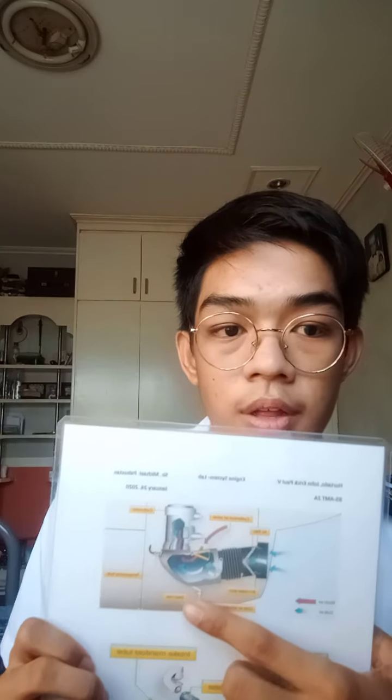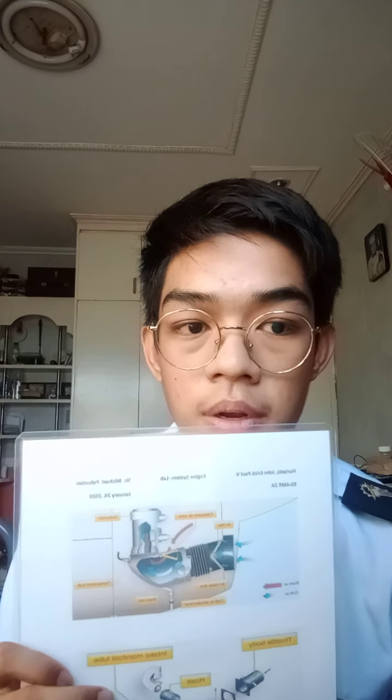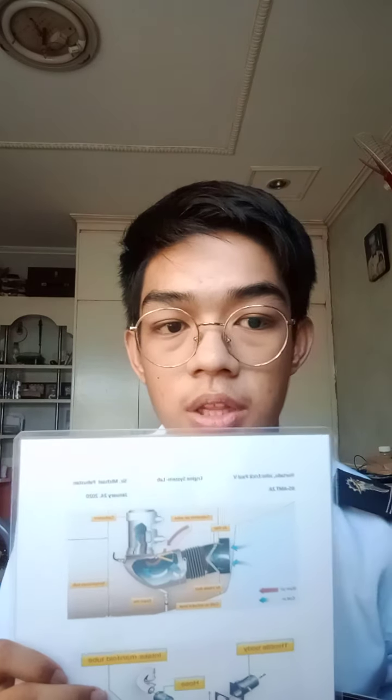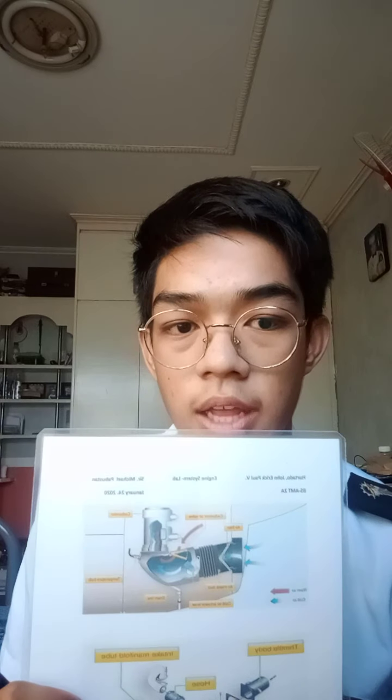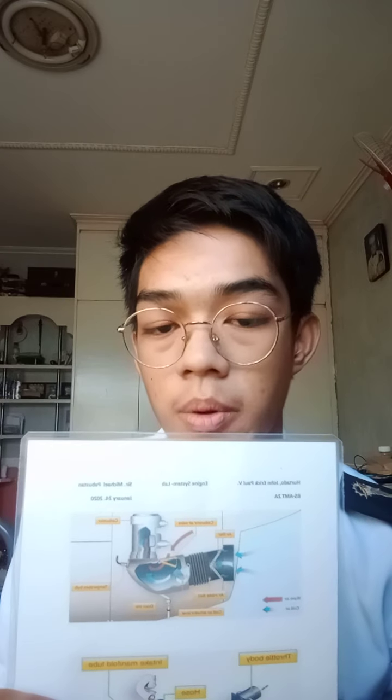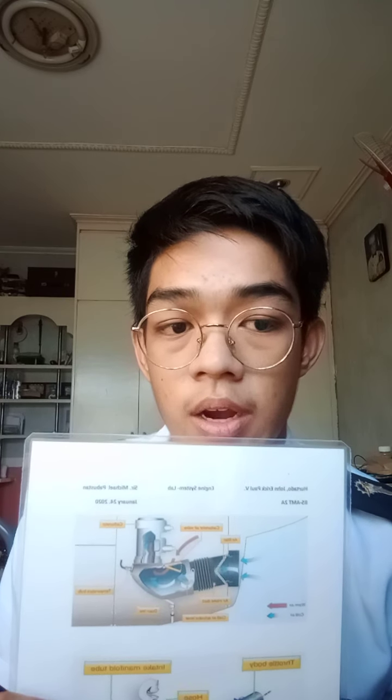So in this diagram, the carburetor normal flow air is admitted at the lower front nose of the cowling below the propeller spinner, and is passed through an air filter into air ducts leading to the carburetor. A carburetor heat air valve is located below the carburetor for selecting an alternate warm air source to prevent carburetor icing.